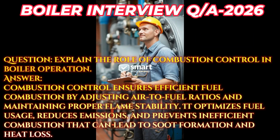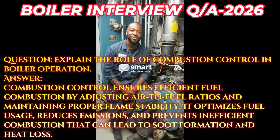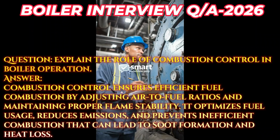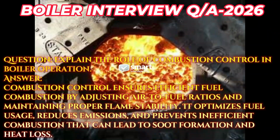Question. Explain the role of combustion control in boiler operation. Answer. Combustion control ensures efficient fuel combustion by adjusting air-to-fuel ratios and maintaining proper flame stability. It optimizes fuel usage, reduces emissions, and prevents inefficient combustion that can lead to soot formation and heat loss.